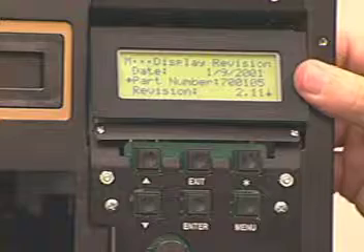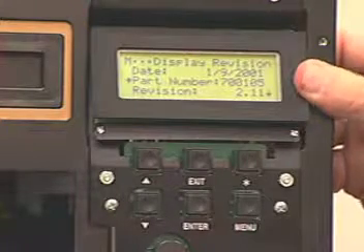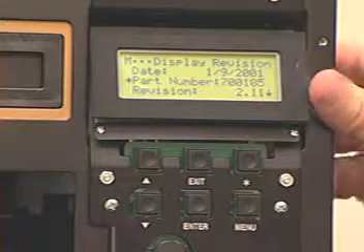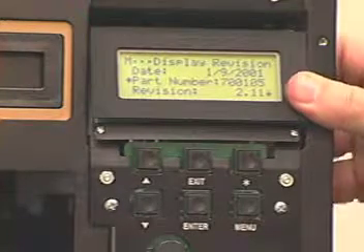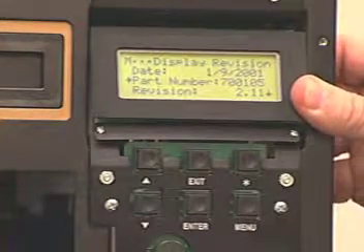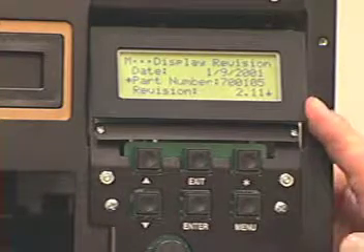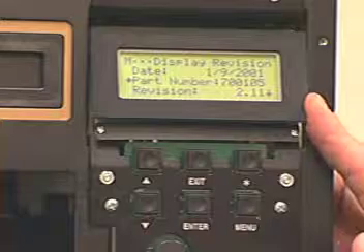If it was 700115, then it would be an Exec 4 board. And the other one that you will see in some cases in the field is 700099. That is the Exec 2 board, and that firmware, if you remember, is only up to version 1.31.